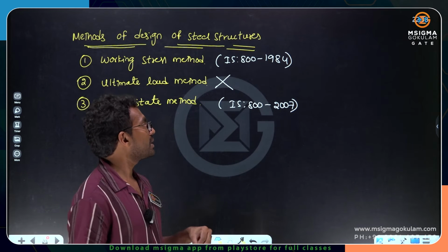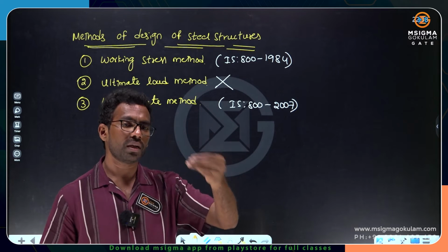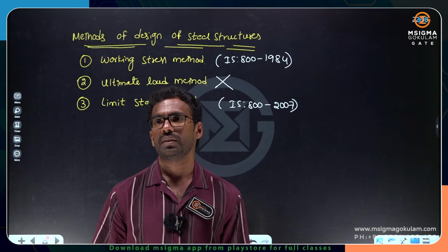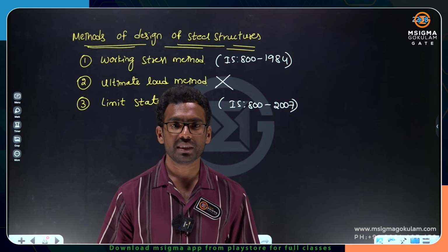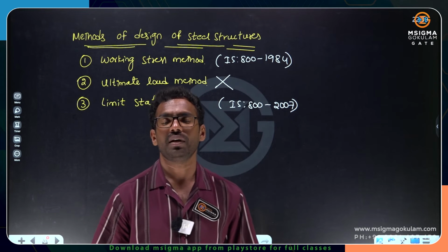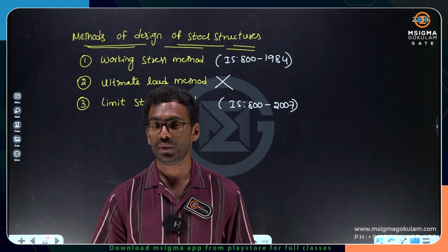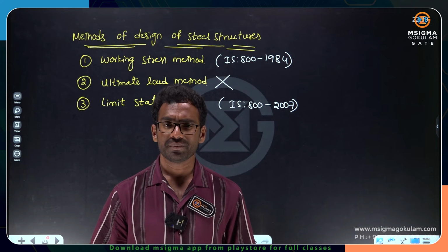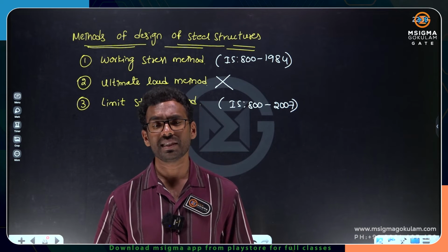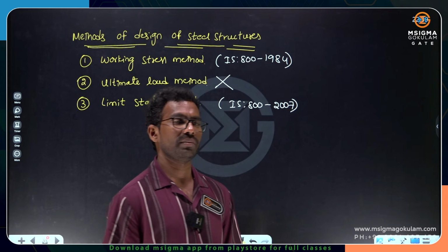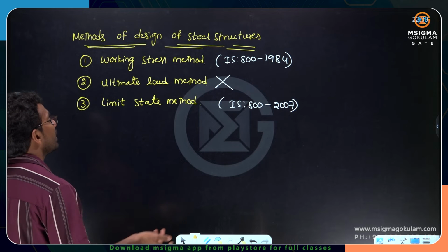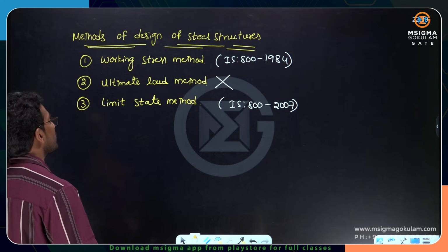That's why the only drawback of the working stress method is that it's an uneconomical method. But safety wise it's well and good, because as long as you are in a low stress condition, the material is safe. Please understand that. That is only the safety format: only material stress should be underestimated, and the remaining are automatically taken care of.